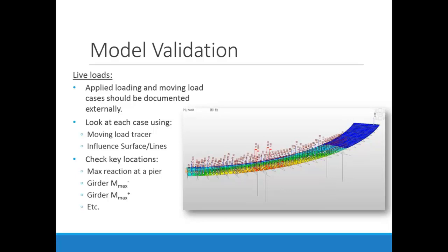Okay, so looking at live load. As always, document the whole way through. Get each of your live load cases on paper, the locations of where each lane will be, and make sure you have all that down on paper before you define your moving load cases.